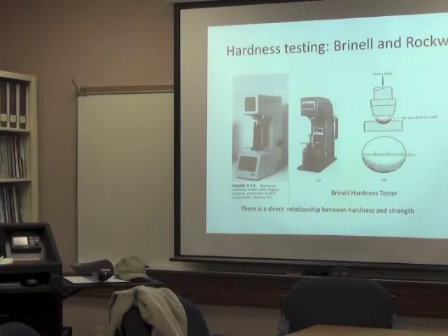Over here, you see a Rockwell hardness test. That's just another way of doing it. Rockwell is very common, and they use an indenter there. They have many different types of indenters, and it works a little bit differently. They apply a minor load, and then a little bit later they apply a larger major load, and then they measure the difference between the indentations. The machine does it automatically for you.